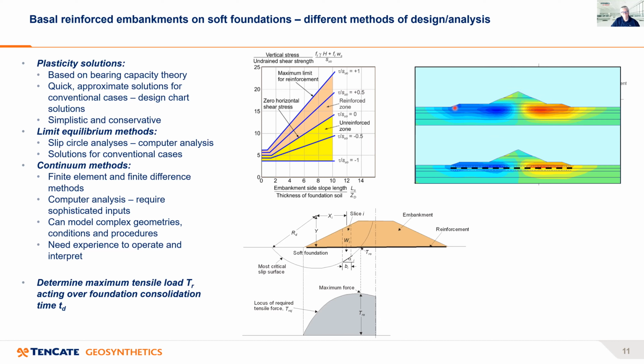And what this method showed, this program shows, is that if you put a basal reinforcement in there, then sure, the shear strains above the reinforcement don't change very much, but the shear strains in the soft foundation soil beneath the reinforcement are much reduced, and this gives the stability for this structure. So these continuum methods today give nice graphical outputs and enable you to easily visualize what the reinforcement is doing.